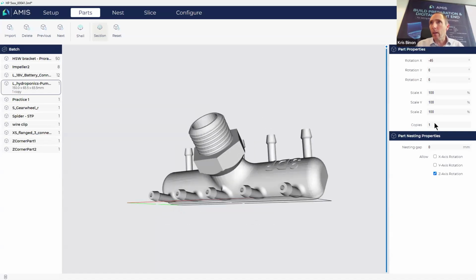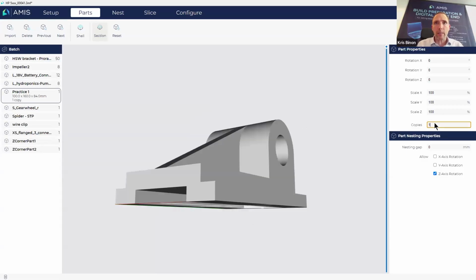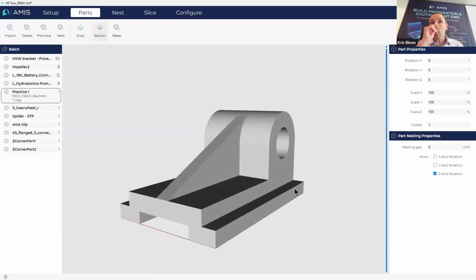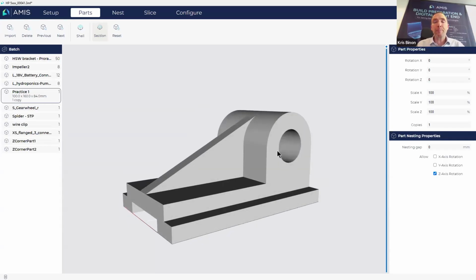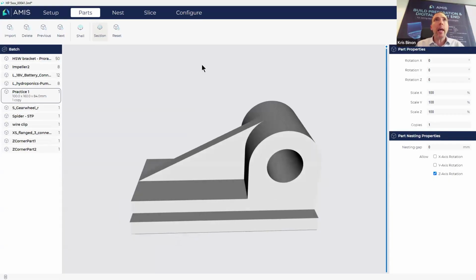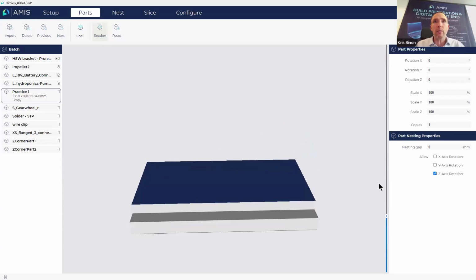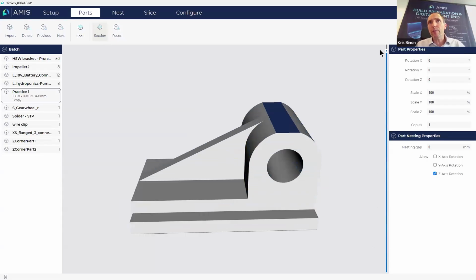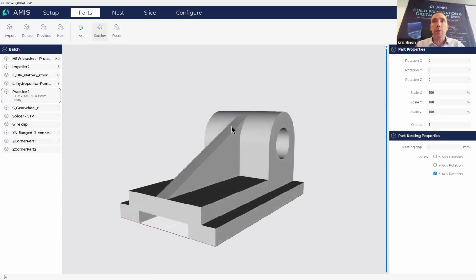There we are. And this one I need 8 copies as well. Over to the next part. And this is an interesting one again. Why? Because it's quite bulky, 10 by 16 centimeters. And as you can see here in the section, it's, well, full. So that's going to either use a lot of ink or binder, or it's going to insert a lot of heat in there. And the customer has allowed me to, well, foresee shelling.